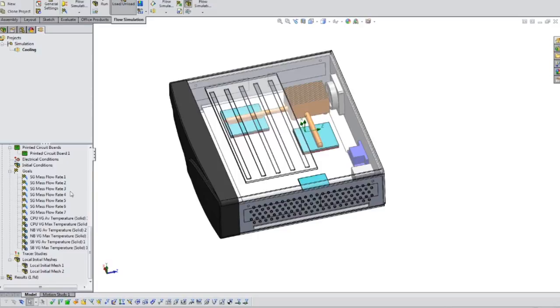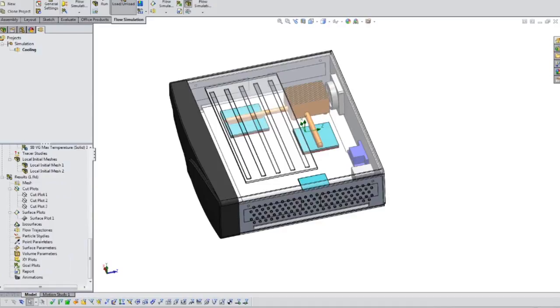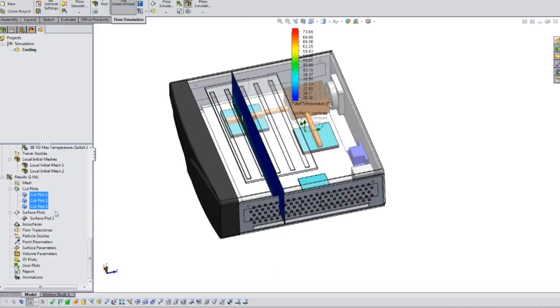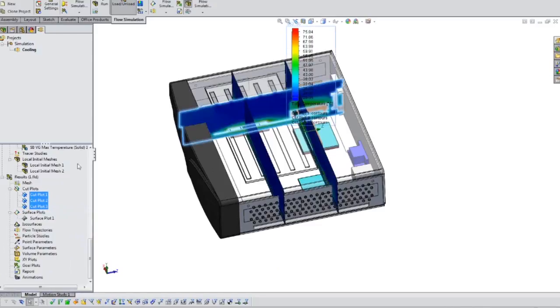If we don't have a material inside SolidWorks or we don't apply material ourselves, it's going to automatically use that material. We tell it what the wall conditions are on the outside of this analysis. In this case, we have it set to a heat transfer coefficient. The environment's at around 20 degrees Celsius, and the heat transfer coefficient is around 10. So I would assume this model is in an environment maybe inside your office, where there's not a lot of convective heat being able to pull heat out of it. It's really got to rely on the fan inside of this model. And initial conditions, we just basically told the software that when this analysis starts, it starts at 20 degrees Celsius, and we want to understand what happens over the course of time.